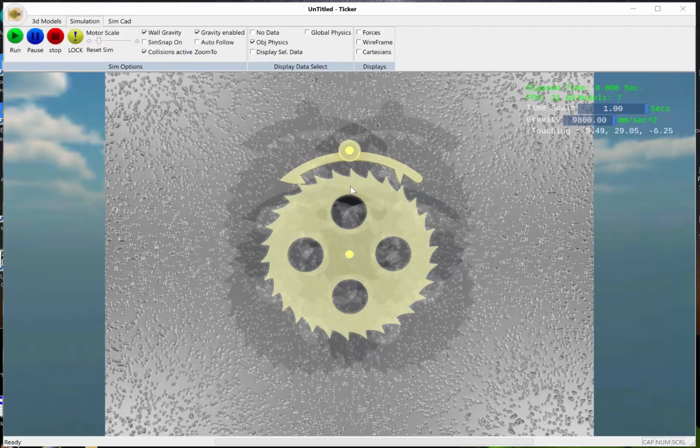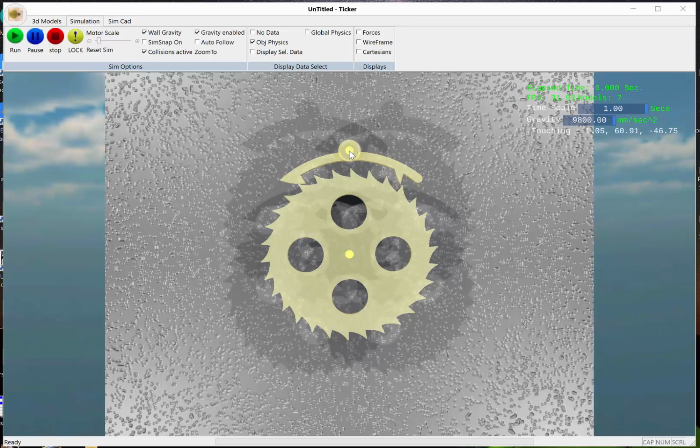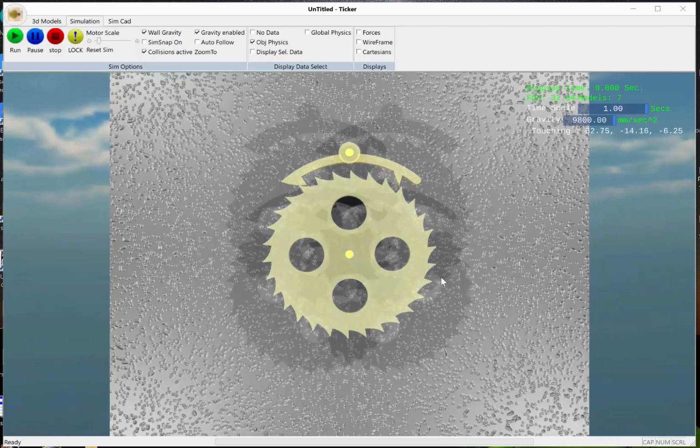Now, to do a pendulum on a real anchor escapement, you would normally use what's called a crutch. A rod would come off of this axle and come downwards, perhaps to the bottom of the ratchet area. It would have a little rod on either side of it, and the pendulum would ride from this shaft down through the center of the crutch. The pendulum would not hang from this shaft, but instead would hang from a bit of spring above it so that the bendy point of the spring is in line with the shaft. The crutch would then push the pendulum back and forth on its own independent held spring. This allows for a higher efficiency of force transfer and will make your clock run longer.